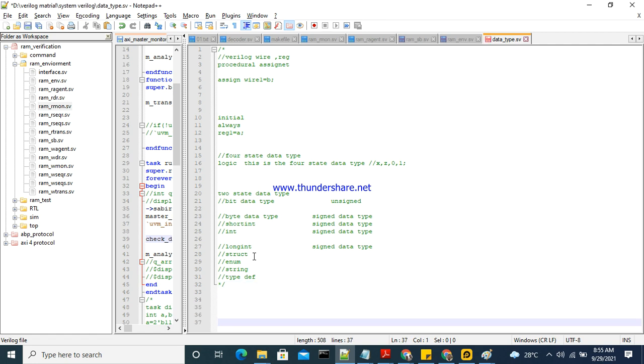So now we start something. Just assume we are writing the code now. This is our module and your module name. Module is a keyword of SystemVerilog and Verilog. So here the module, and then the module name. This is the module name, meaning the data type. This is a user defined name, so you can keep anything you want for whatever you are writing.